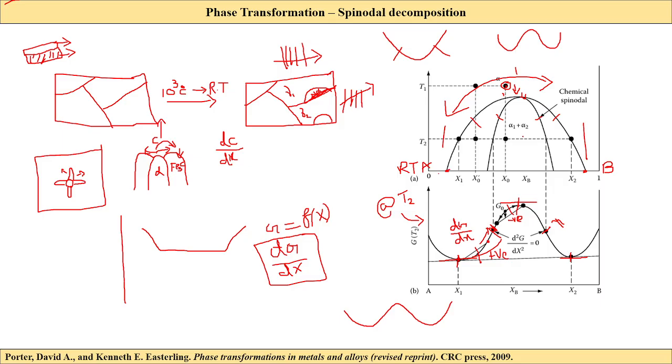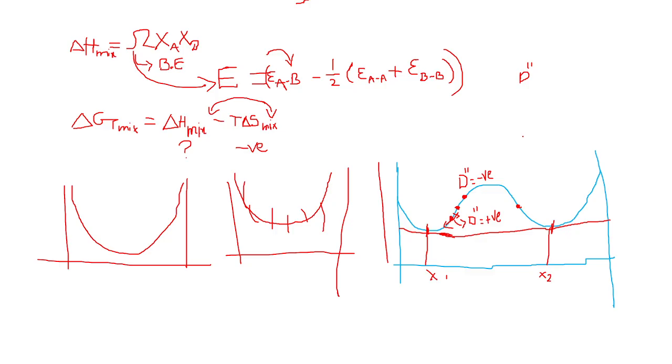So that means to form phases of the same crystal structure but different composition, you need to have only the movement of atoms across the grain boundaries. That's all. There is no movement of atoms from one phase to another phase. It's just the movement of atoms across the grain boundaries, and you have your two different phases. That's all. So that is known as spinodal decomposition. Spinodal is more like a spontaneous decomposition reaction where you do not even need the nucleation part.